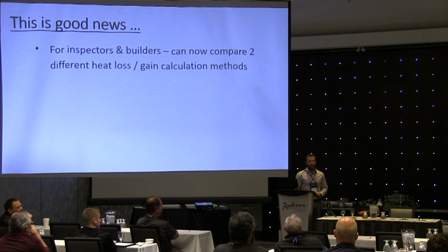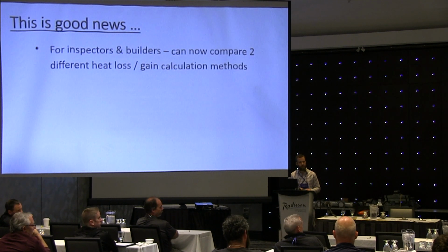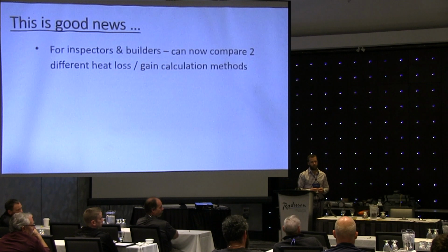20%? Yeah. 10% fine, 15% fine. As soon as we start getting 20, 25, I might ask people to talk at least and see where this discrepancy is coming from. Another possible explanation is that in forced air heating systems, the increments of BTUs on the appliances are like 20,000 or 30,000 steps, because they're built with one heat exchanger section, 2, 3, 4, and there's steps of 10 to 20,000 BTUs.